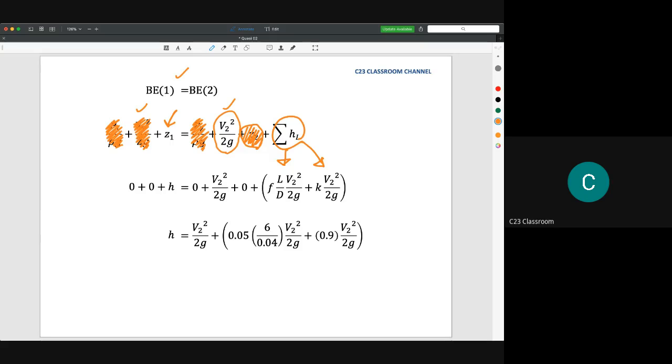Okay, so please let the value of Z1 here, that means the water level at inlet, be an unknown, or we can consider it as one, it can be changed, because now we need to build an equation to do the integration. So we substitute the value of Z1 with H here, and then this is the value of major loss and minor loss. So for sure we cannot calculate the value of V2 because we don't know what is the value of H.